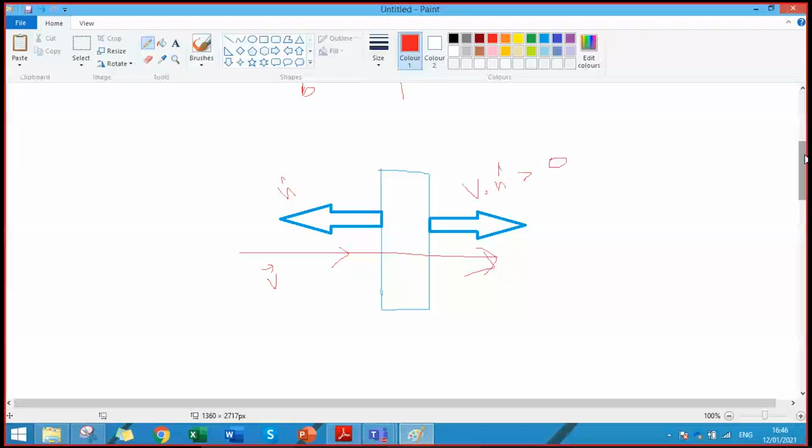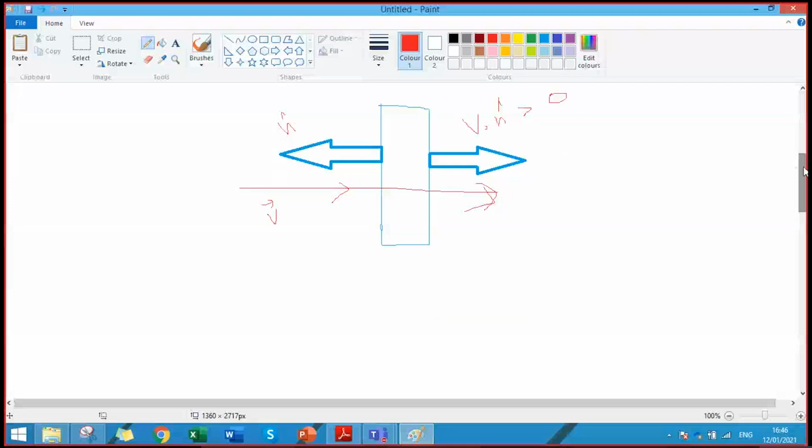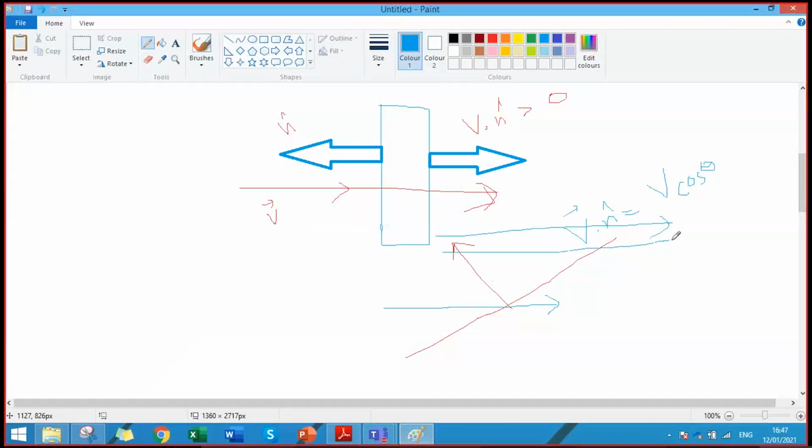Yes, sir. Clear. Moreover, this v dot n will solve many other problems. Let's say the control surface is inclined like this. The area normal would be like this, right? And if the flow is horizontal, it means the whole surface is not participating in the flow. So v dot n would be equal to v cos theta. It will automatically account for the amount of flow, because the flow beyond this area would pass above and will not contribute to the control volume.